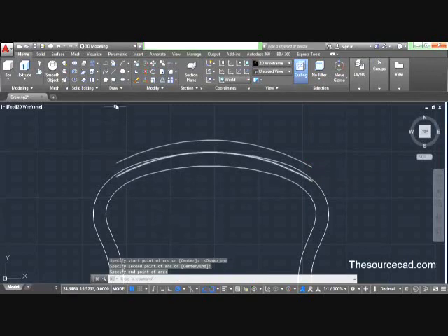Now we'll join both these endpoints using a line. So go to line and select this point, and we don't need to join it from that point, so make a random point. Oh, it snaps to that point. That's why I said that you need to turn off O snap. So turn it off and now make a line. Okay, like this.